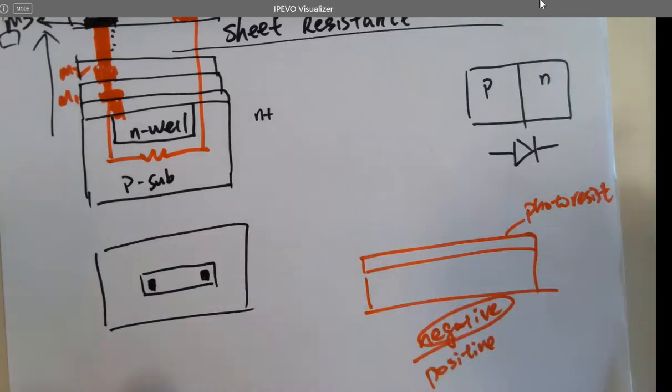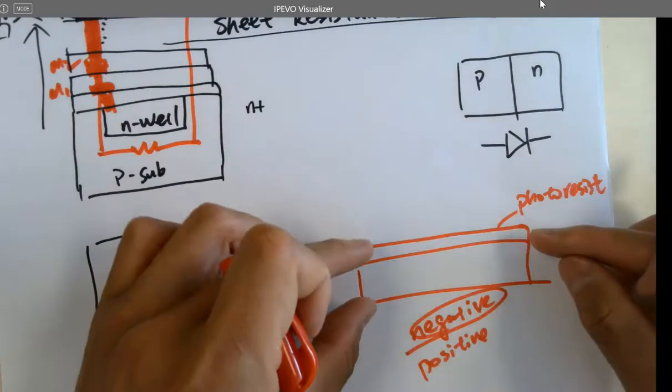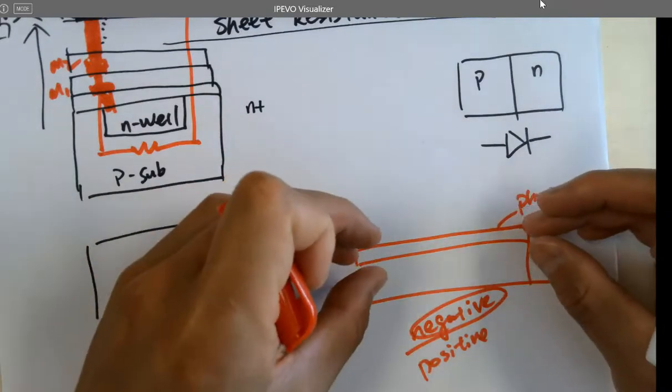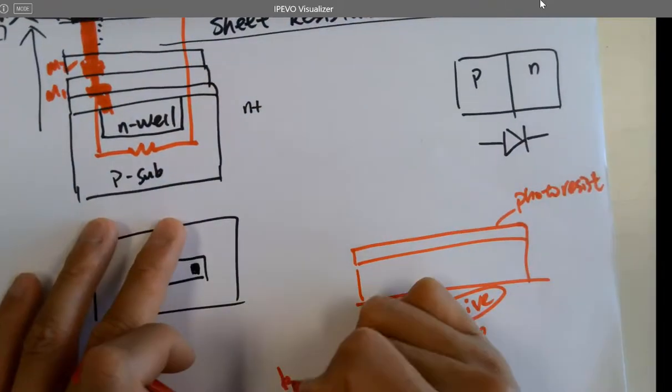So what you are laying out right now, you know what? You're laying out the mask. You probably don't know that. So layouts are masks. You have different layers of those for the circuit. You are thinking you are laying out the circuit. No, you are laying out the mask. There's nothing about circuit. They will be printed on the wafer as a circuit in the future, but they are not circuits. It's just masks. All different layers of masks, and based on different processes, they put the very bottom mask over here and make one layer, and then start the second layer, metal 2, metal 3. It's called a bottom-up process.